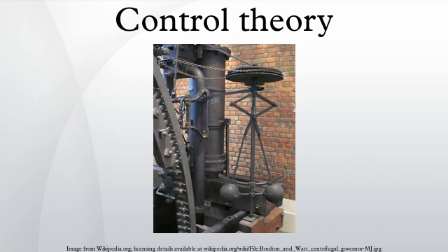Constraints. A particular robustness issue is the requirement for a control system to perform properly in the presence of input and state constraints. In the physical world, every signal is limited. It could happen that a controller will send control signals that cannot be followed by the physical system, for example, trying to rotate a valve at excessive speed. This can produce undesired behavior of the closed-loop system, or even damage or break actuators or other subsystems. Specific control techniques are available to solve the problem: model predictive control, and anti-wind-up systems. The latter consists of an additional control block that ensures that the control signal never exceeds a given threshold.